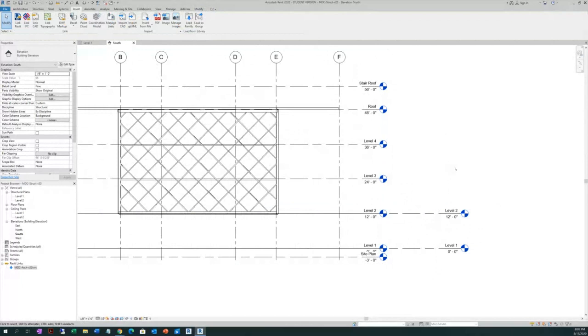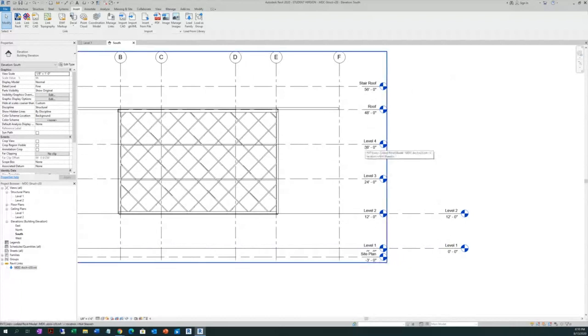I want you to have all your structural levels on the right side. This is going to be your structural levels. And at one point, we are going to unload this architectural file, because my intent is that you have your framing, leave it alone, and when the architect sends you a notification for coordination, then you load it and see what you need to coordinate.